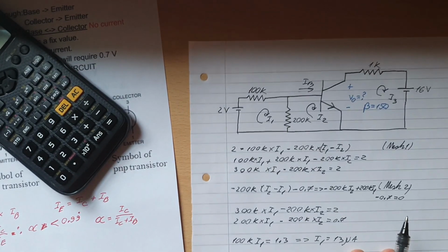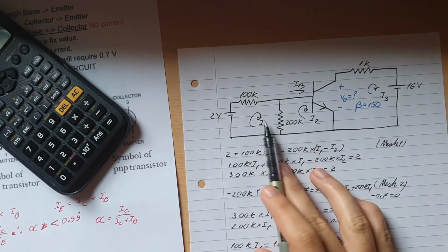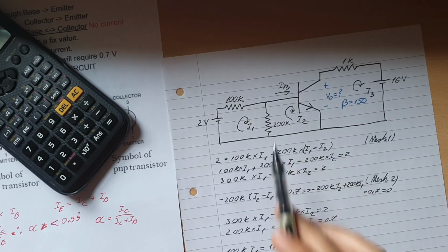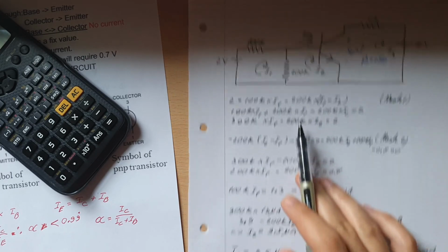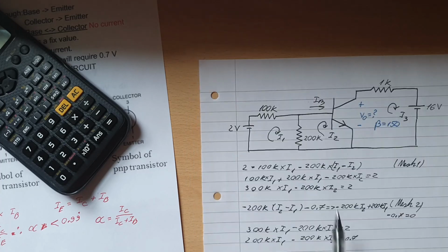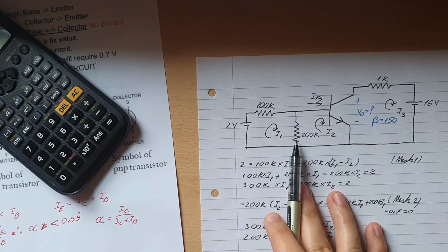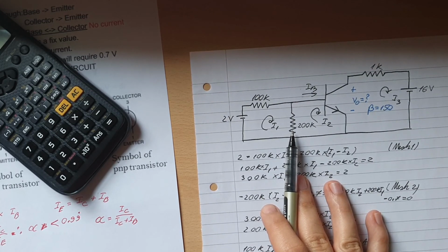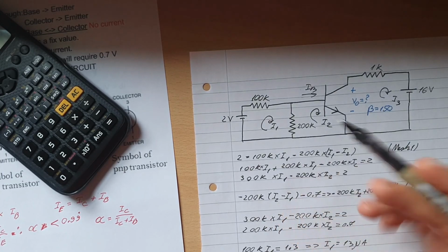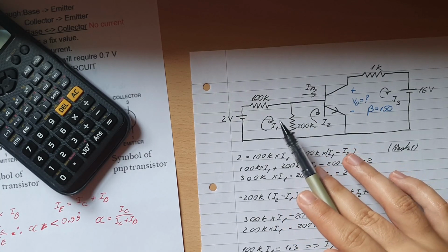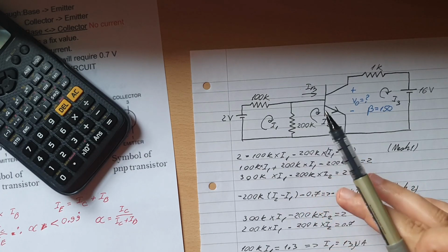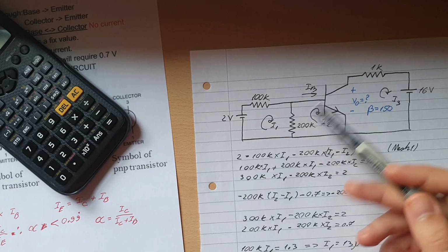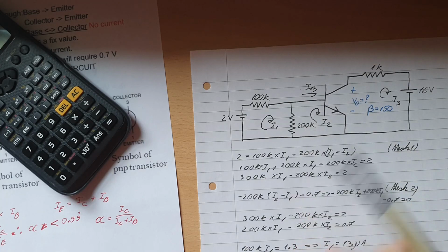And that's how you solve it if you want to apply mesh analysis instead of Thevenin's theorem. This will work because this is a DC circuit, but if you try to apply simultaneous equations or anything else in an AC circuit, then you will have quite a problem. Anyway, of course, unless it's made out of only resistors. If it's made out of only resistors, then you can easily apply the AC theory to it. But if it's got capacitors or anything else, then that would make it a lot more complicated to use mesh analysis.